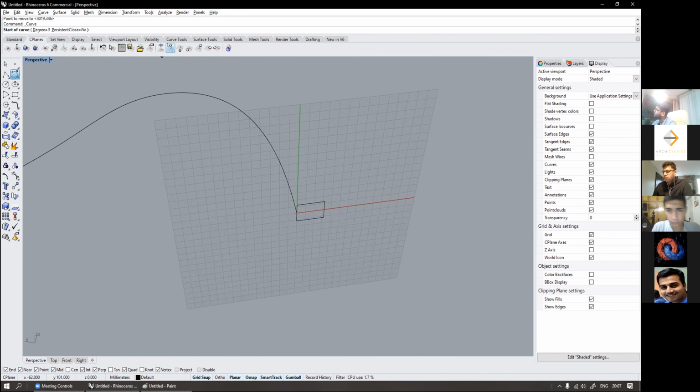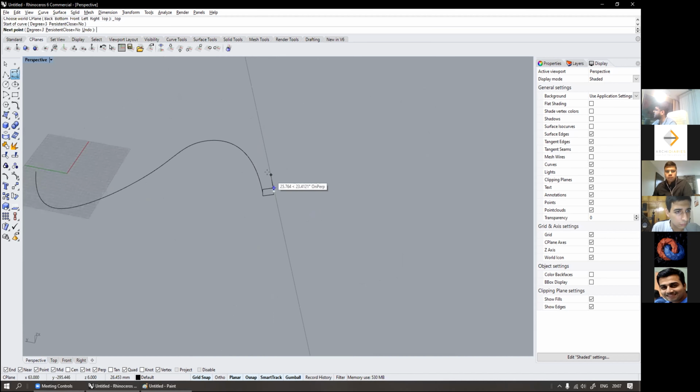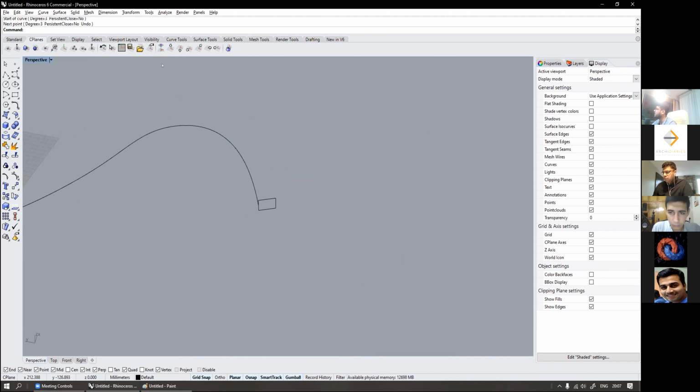So first I'll have to make this go again to the wall top, right? So I'll select this option over here and it has gone back to the wall top. And then I can create a spline again like this, something like this. Everyone's good with this?